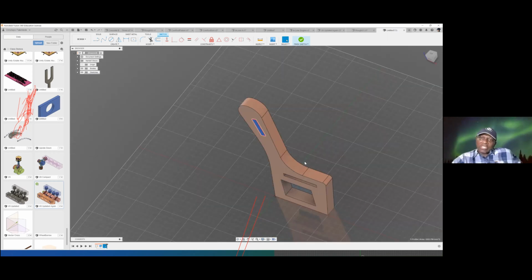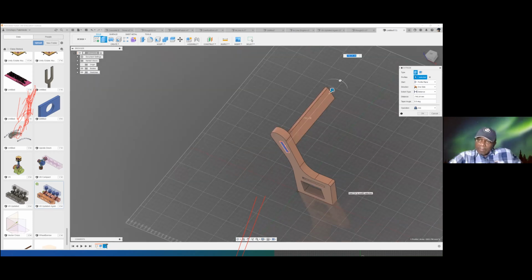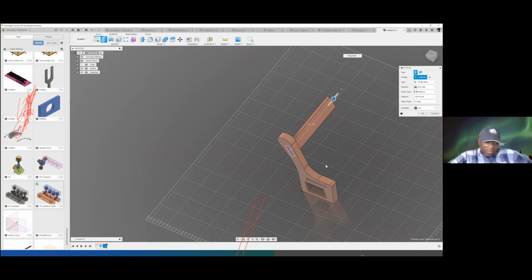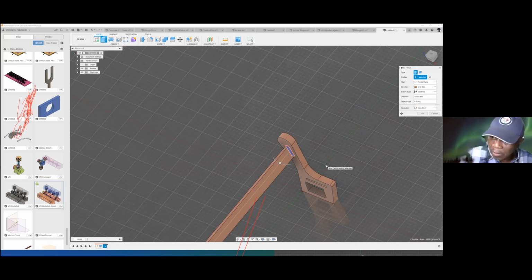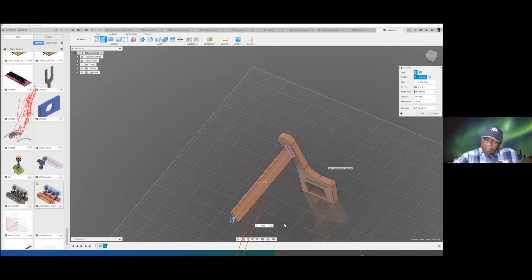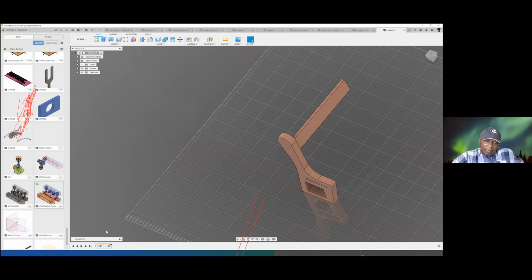So if I go back to the sketch and put press pull, what I can do here is that I can press pull it, and I can create the backrest that way. Let us say I want that to be 1000. Let's say minus 1000. Okay, so now I don't like that, because you can see that it came in the same color.